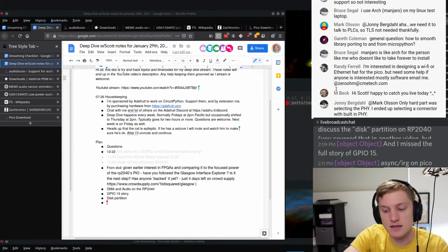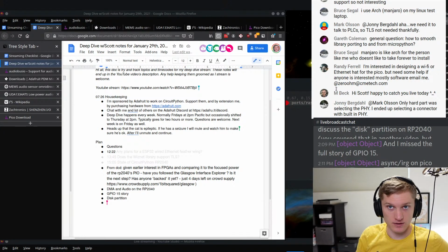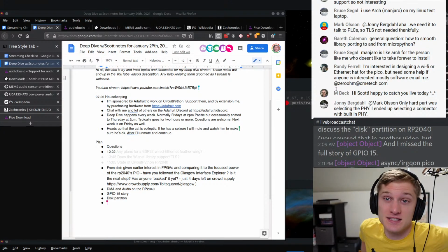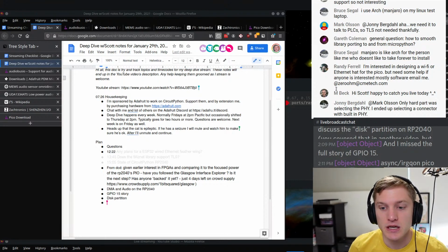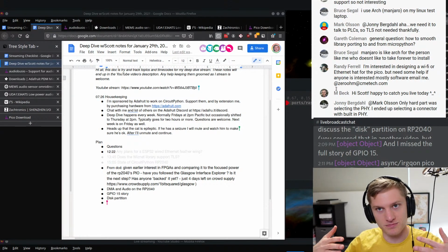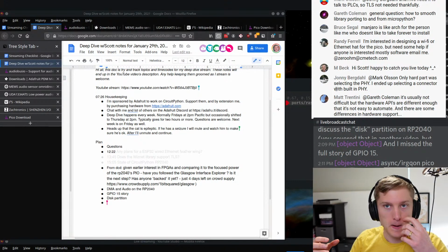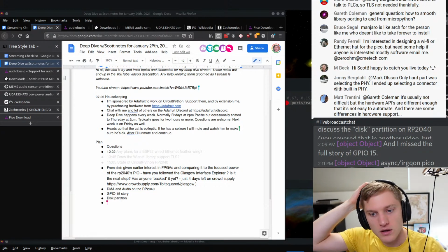And then lastly, I just looked at PDM in, which is the microphone that we have on the Circuit Playground, and it looks very easy to do with a PIO. So I think I'm actually just going to try to knock out all those three. I was originally just going to do audio PWM, but I grew what I wanted to do because a lot of the code is shared, and I wanted to centralize it from the get-go.